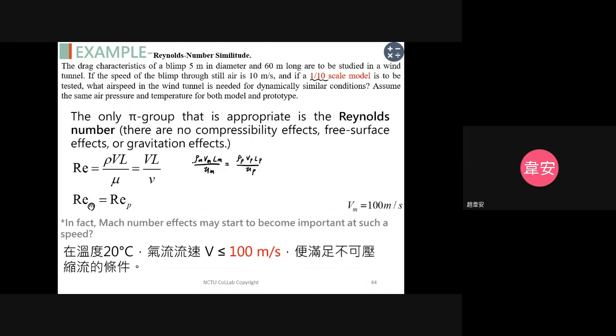So the density is the same between the model and the prototype, and at the same temperature and pressure, the viscosity is also the same between the model and the prototype. So finally, we know that V_m, the velocity in the model, divided by V_p, the prototype velocity, is equal to L_p divided by L_m.